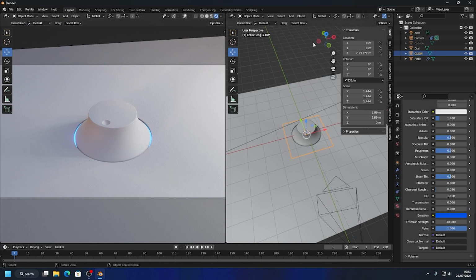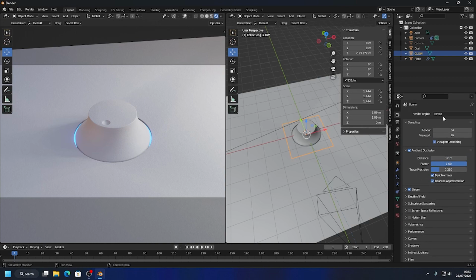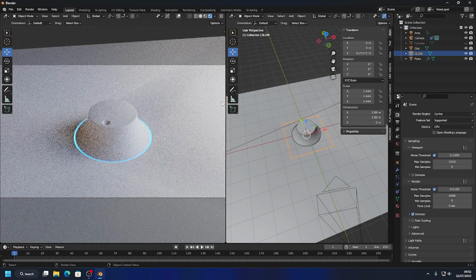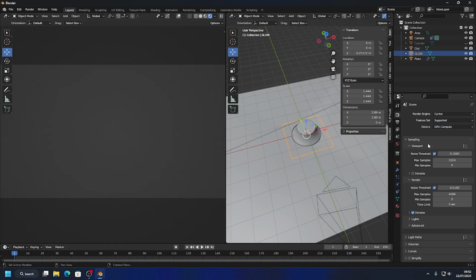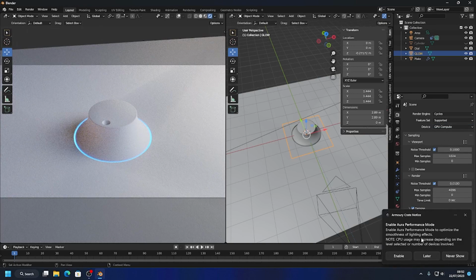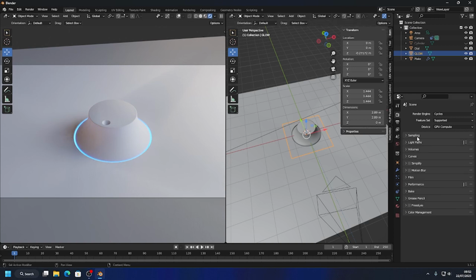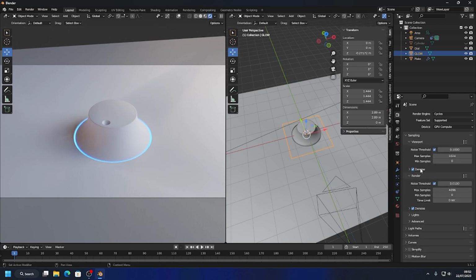I'm gonna just be a little bit extra now. Let's go switch to Cycles. So this is just me messing around now with the lighting, but I can go to Cycles. I'm going to change this to GPU sampling, GPU compute. Don't worry about this notice. It's telling me, oh, you can change the RGB colors on your motherboard and all of this fancy stuff, but I don't like the RGB stuff. Anyway, I just turned the denoising on.